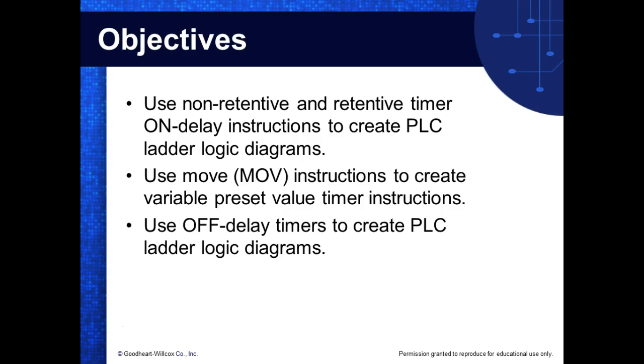Then we have what we call a retentive timer and a non-retentive timer, and this is true on most PLCs. The S7 software for Siemens has these two categories, retentive and non-retentive. We're going to pick up a new output instruction called move, which is a very, very powerful instruction. One of the big things a computer can do is literally move things around, move binary information from this location to that location or vice versa. Every programming language that I've ever seen supports some type of move instruction.